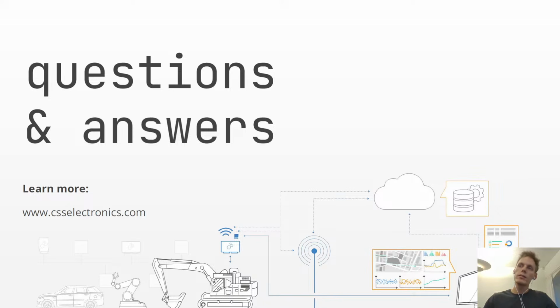The trick is, even if you get access to the raw CAN bus data, you will need to be able to decode it. And within the electric vehicle area, it becomes more complex because it typically involves multi-frame communication. The CANedge is probably what I would recommend here, but whether it's a CANedge 1, 2, or 3 doesn't matter. But I would recommend to go to our case studies section because we actually have case studies for the most popular electric vehicles, including the Hyundai and Kia brands, all of the Volkswagen brands, the Tesla brands, and more. So you can find basically details on how you would record data from these particular types of vehicles.